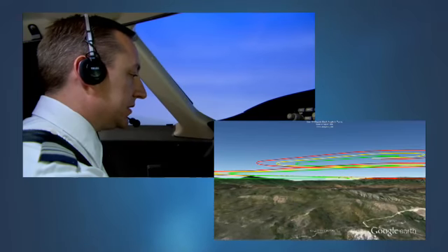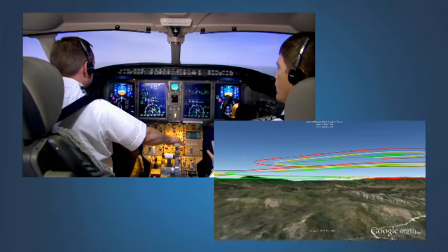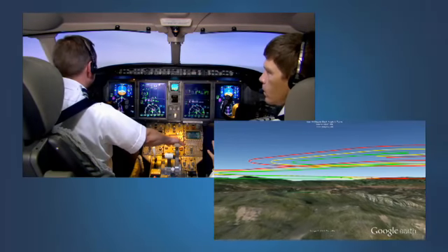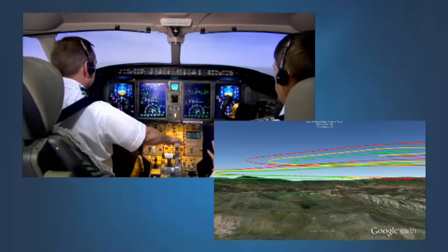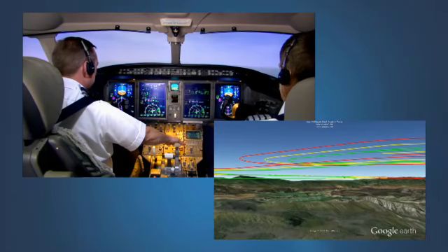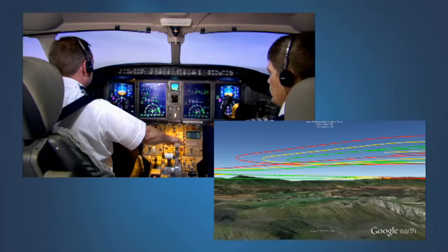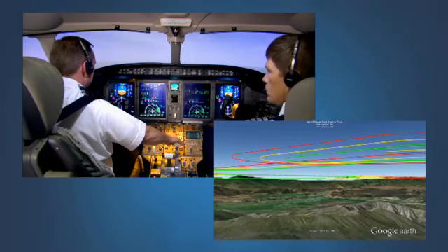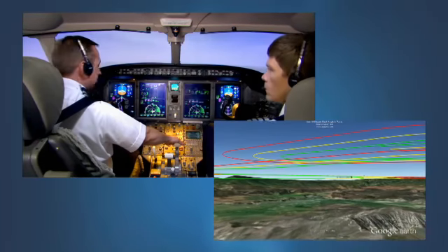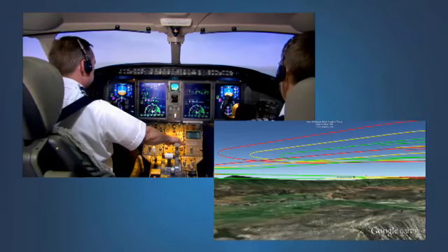We'll use the APU assisted one, so we'll get the engine restarted if we can, and we'll proceed and get a clearance over to Denver as we discussed previously, and just not go back into Aspen. Concur. We will probably need to climb to at least 17,000 or flight level 190. We can ask ATC, but that shouldn't be a problem. Roger.